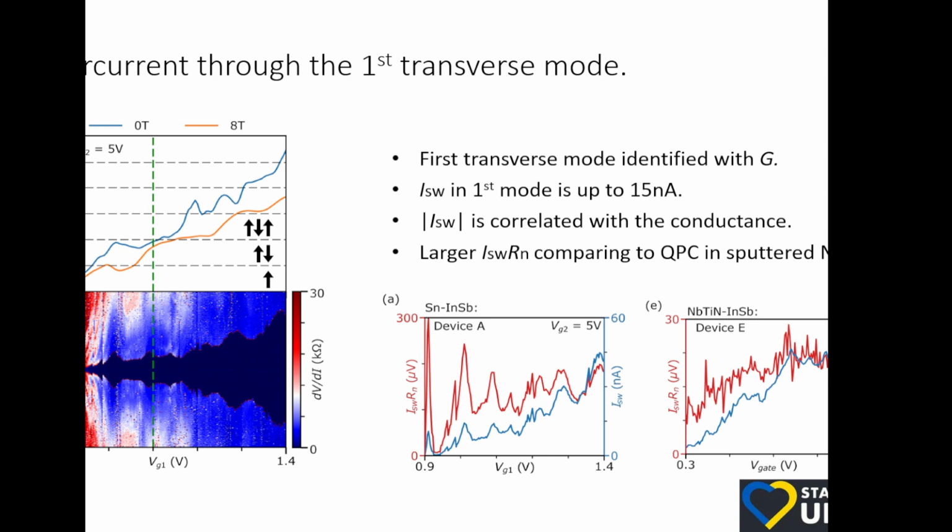And fortunately, in that same region, when we measure supercurrent, we have quite a bit of signal. So in this case, the 20 nanoamperes of supercurrent, pretty sharp switching. Again, there are ups and downs. It's not just a plateau. There are some interferences. But there is a signal. We can study this signal in the few subband modes. So this will be one subband. There'll be a second one here, a third.